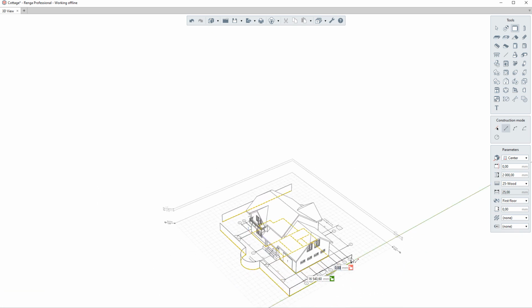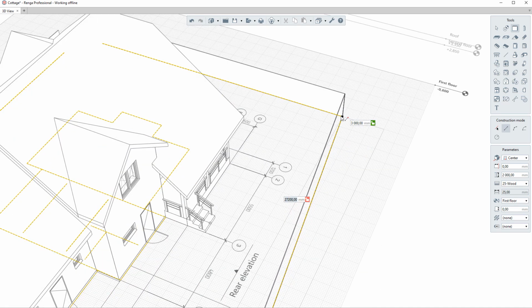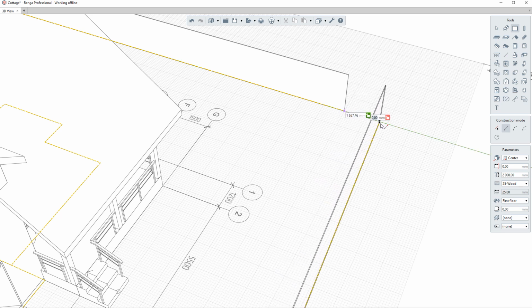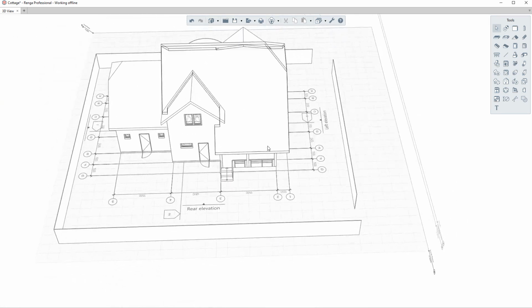Change direction to finish the fence. Set the value along the green line 25,000 mm. It is necessary to finish a new wall at the end of the first wall. For that, call a tracking snap. Keep the mouse cursor at the end of the first wall. When the point changes color, use the mouse cursor to set the tracking direction to the expected point. Click the left mouse button. Press the Escape key twice to complete the command.